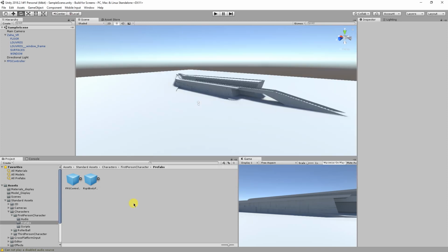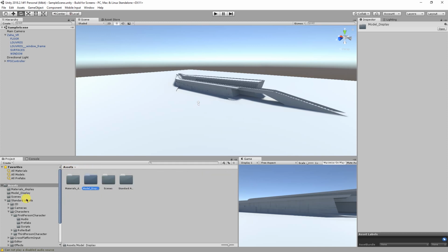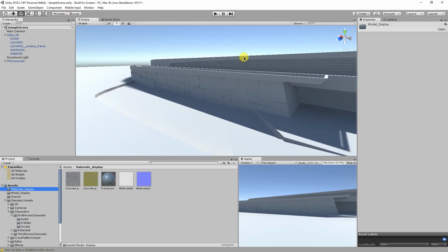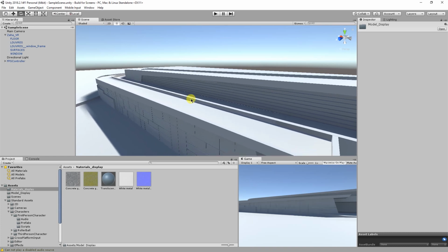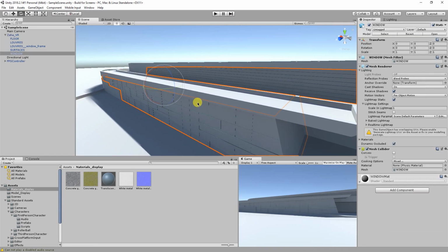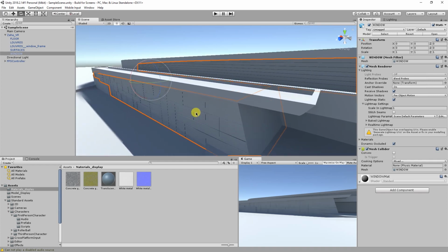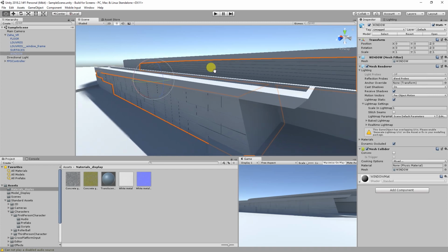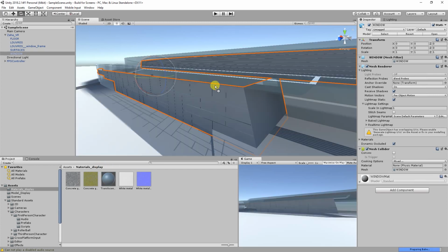And then when you click back onto your Unity, in the assets, there it is. In assets, materials display, and we've got some there. Great. If you select the object group Windows, this is where, seriously, exporting the right way is just so handy. And just drag that over the windows. We started with a translucent texture.